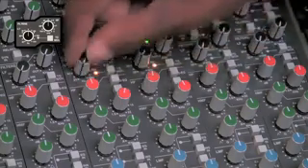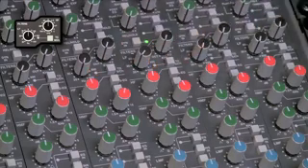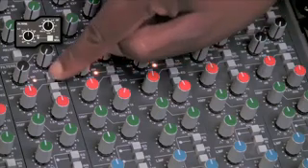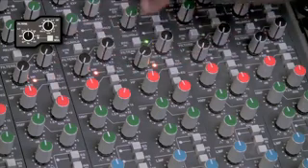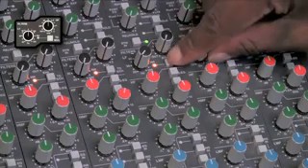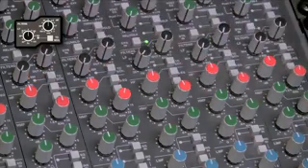As an example, you could use this to heavily compress a kick drum. But what can happen with heavy compression is you'll start to squash the transients. By rolling off the low frequencies using the to sidechain option, you can roll off all the low end from the detector circuit of the compression, allowing it to only react to the lower frequencies or the higher frequencies depending which roll off you use. And this will allow some of that low end frequency back into your sound.